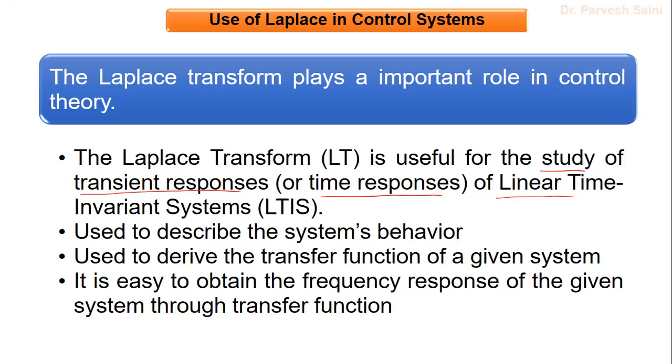So by using Laplace transform, it becomes convenient for us to analyze the transient characteristics of the given system, right? Like we can analyze the rise time, peak time, settling time, overshoot. So we can analyze these transient characteristics or dynamic characteristics of the given linear time invariant system, right?